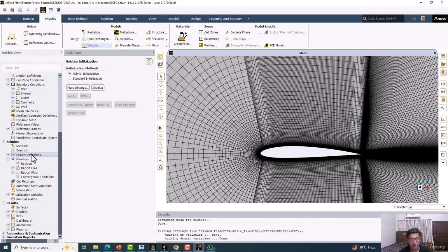For the lift coefficient, it will be the opposite, because one component will be along the negative x-axis and one component along the positive y-axis, but the values will be flipped. So now the angle will be with respect to the y-axis. The x value will go to the y component of the lift coefficient, and the y value will go to the x component, but the x value will be negative.